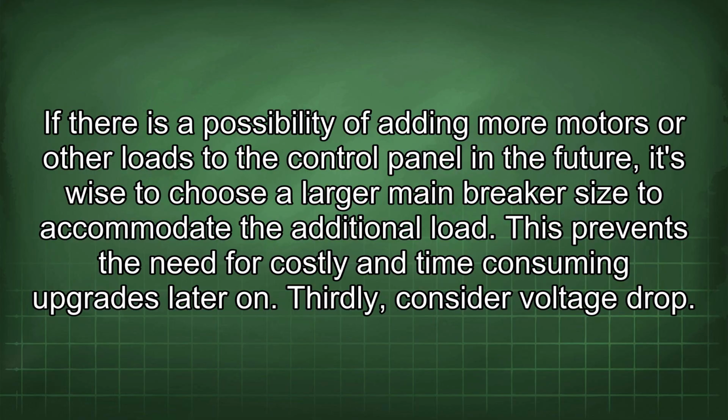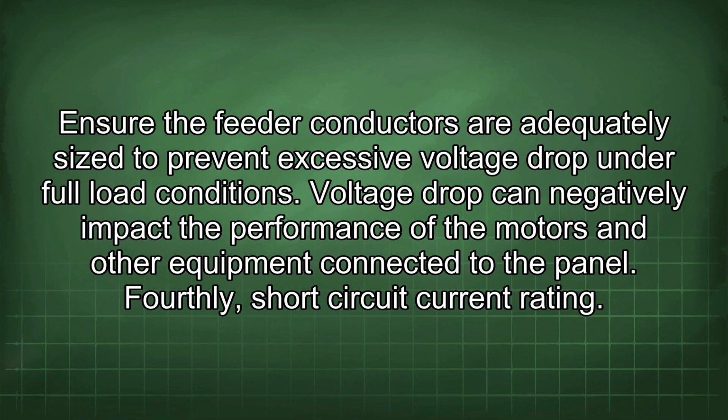Thirdly, consider voltage drop. Ensure the feeder conductors are adequately sized to prevent excessive voltage drop under full load conditions. Voltage drop can negatively impact the performance of the motors and other equipment connected to the panel.